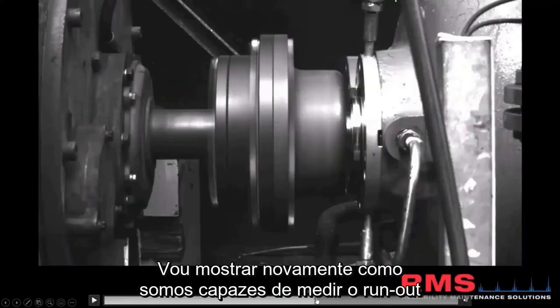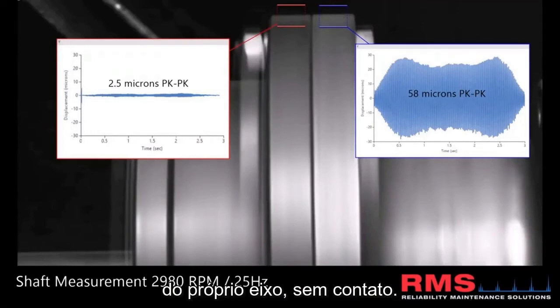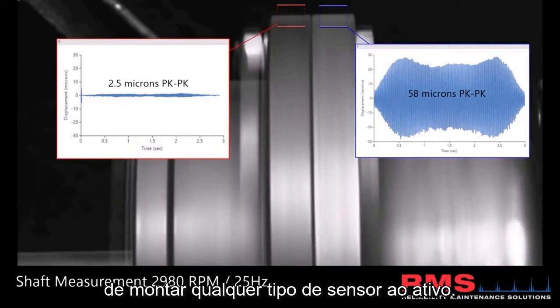We're actually able to measure the run out there of the shaft itself. Again, non-contact, right? You can't make contact, and we're leveraging the fact that a camera can measure this without actually having to make contact, which would be impossible. I mean, similar to what a prox probe does without it having to affix any sort of thing to the asset.